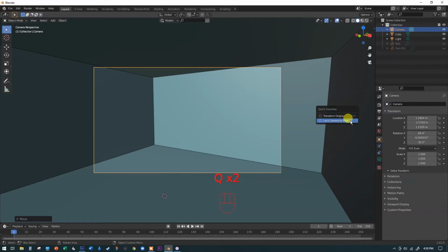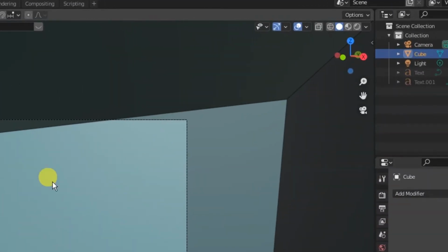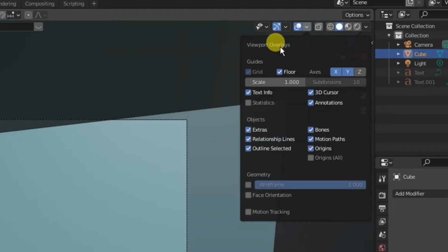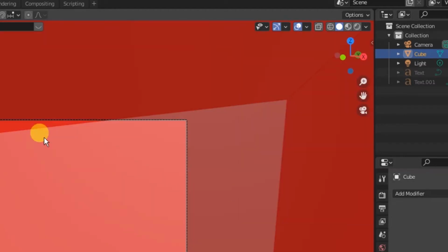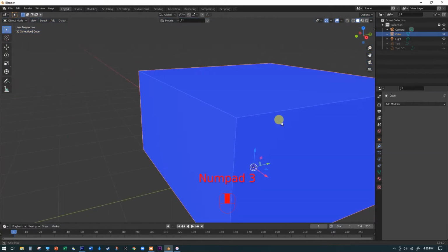It is. I'm going to leave that turned off, and I'm going to talk about the other thing that can be tricky about this. And this is true for a lot of the different techniques that I'm going to show you here. I'm going to come over here to the viewport overlays and just be aware that face orientation is an option we can do. And right now everything is red. Red, that doesn't sound good. So I'm going to exit out and say, oh, look, it's all blue on the outside.